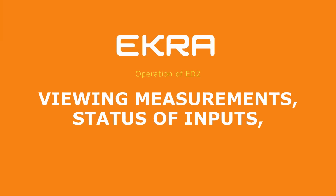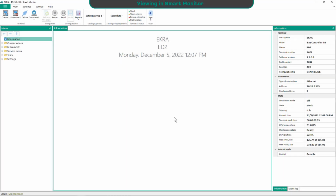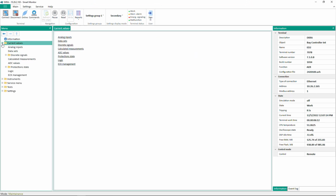In this video tutorial, you will learn how to view measurements, the status of inputs, outputs and logic in the ED2 device. To view the measurements and states of IED signals in the Smart Monitor software, open the Actual Values in the device tree. Actual values of analog measurements can be viewed in the Analog Inputs section.